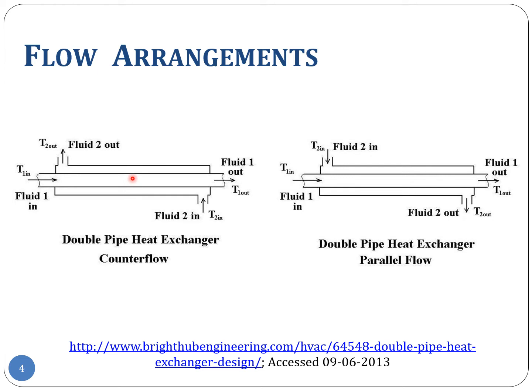So there is heat transfer occurring, and that's all that one needs to look at. So the equations that we derive for the temperature variation along the length of the heat exchanger would be valid for both counter flow as well as parallel flow. It is only the end conditions that would be different for these two flows.